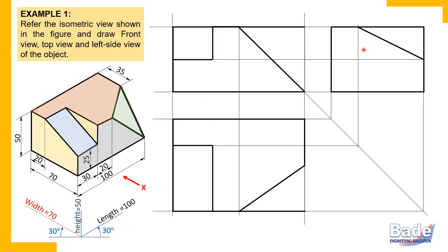Now this triangular surface in the side view, and it's very important again. Listen. In the side view, we should identify these three corners. Okay. So this corner, try to understand. It is on the right side. But for side view, right side, left side, that is insignificant, because in side view, we cannot differentiate right side and left side. We'll check it. It is on the back side. This corner is on the back side.